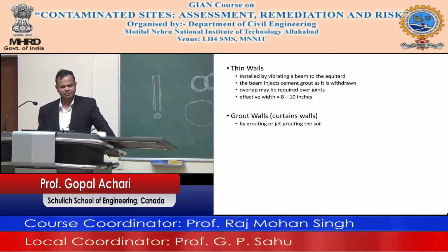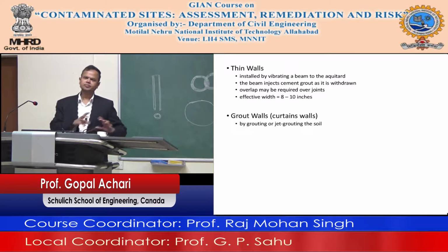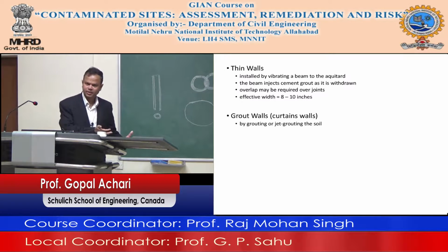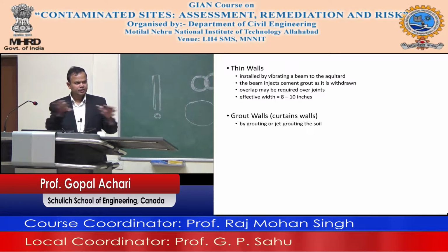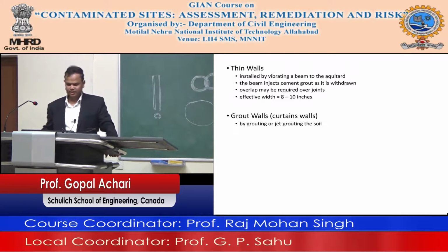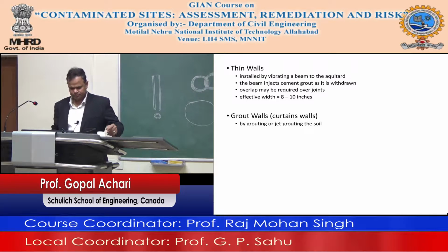Okay, so below the landfill waste, you have a pipe which carries the leachate away, so there is no water buildup, and below that are the two layers that provide protection to the ground below the landfill. One of them is an HDPE liner, and the other is compacted clay. All right.